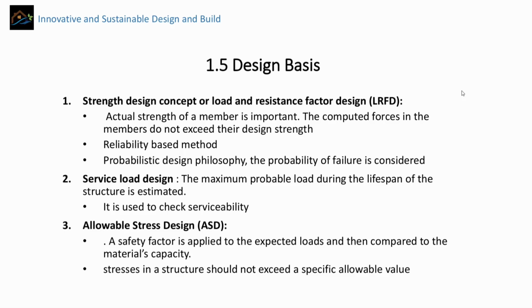The second one is service load design, and this design principle is used in order to check serviceability of the concrete structures, and this comes from the idea that the maximum probable load during the lifespan of the structure is estimated. So we estimate the maximum probable load on a building, and then we say that this is the maximum load, and therefore each element should be designed accordingly.